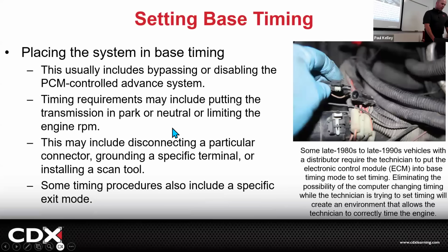Right? And then one of the things that we'll do pretty commonly is set the timing. So if it has a distributor, this is a little bit more about service, more so than maintenance. But let's just say California, did you know they have to verify the timing on a vehicle when you get a smog if it has a distributor? So on a newer car, the computer controls the timing. The computer monitors the timing.